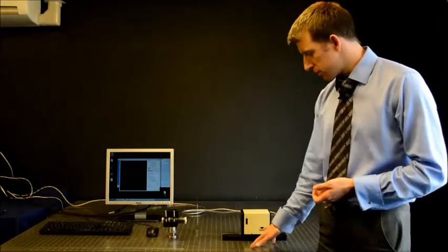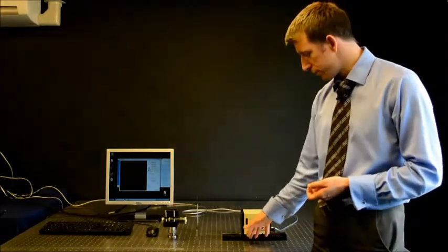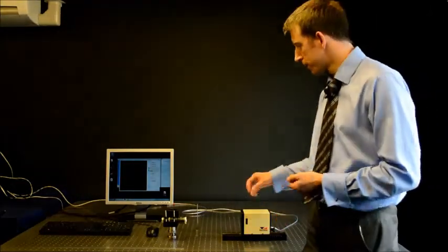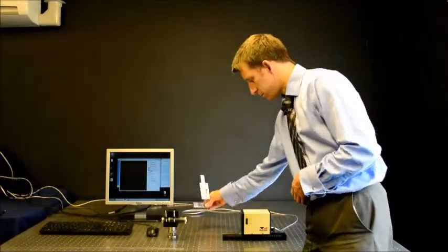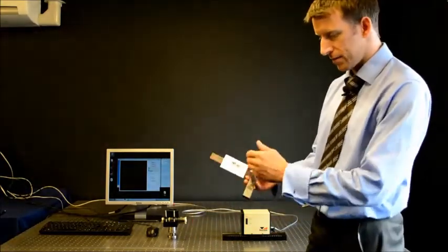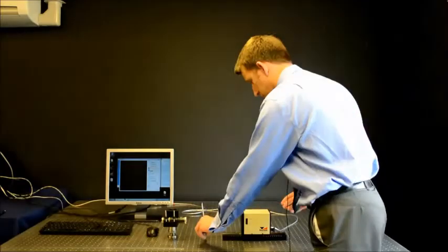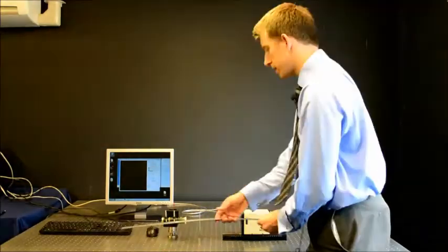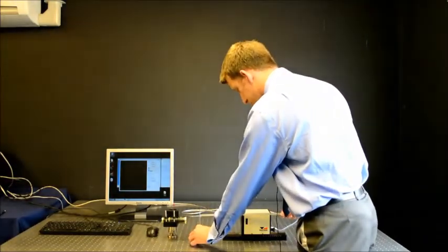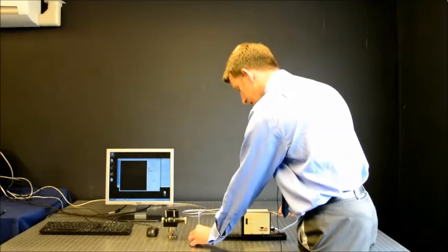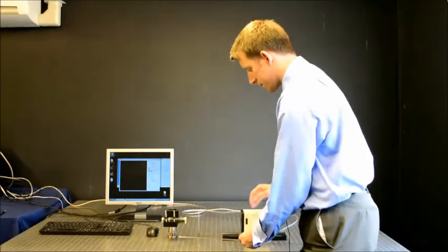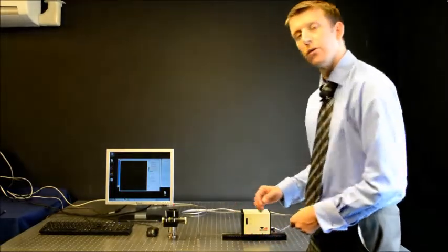Having set the position of the PSL Profiler to 100 millimeters on the rail, one can use an alignment aid. Here I have simply a business card on a set square, and one can measure the distance of 200 millimeters from the alignment aid to the front face of the PSL Profiler.